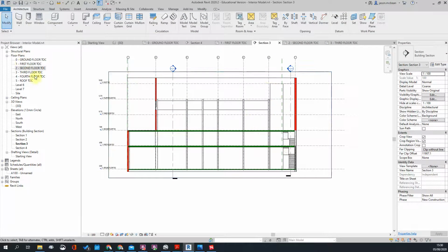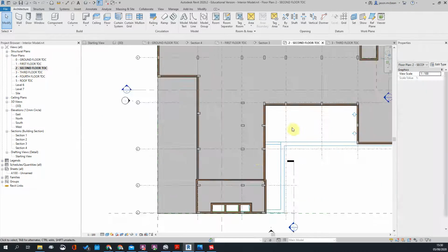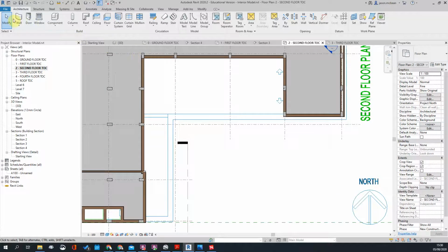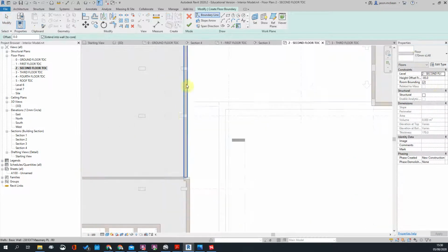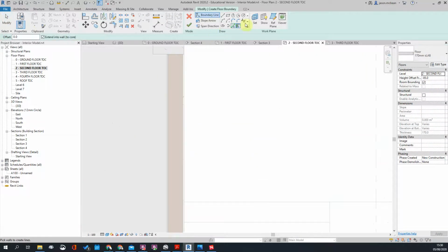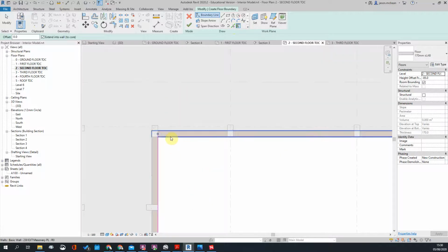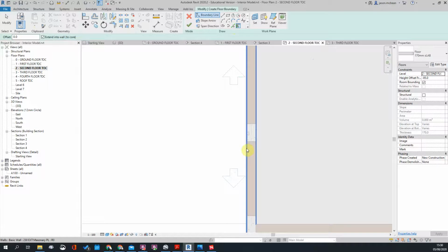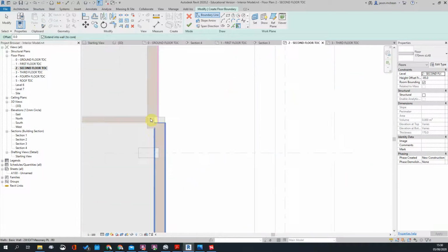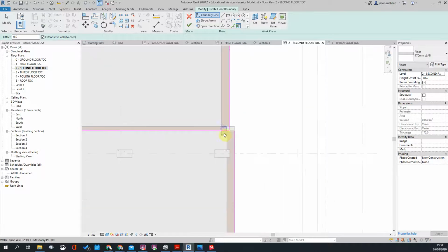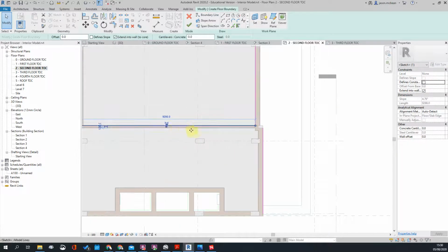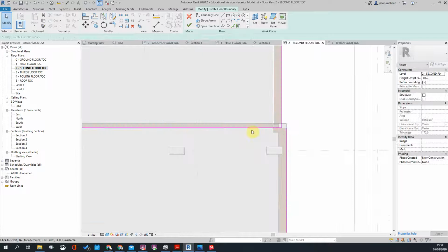Okay. Now what's nice, let's go to my second floor. I've got one more slab to put in. So we're going to go floor slab and it's going to be 170 minus 85. So remember, pick the external faces. So I'm going to use the wall tool. External side, external side, external side, or I can flip that around on external side. So this one is going to jump that way. And that, do that. I'm going to move it to there.